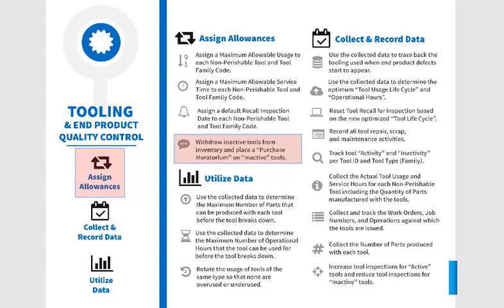So basically, if you implement a system to denote intelligent tool ID numbers and aggregate tools into family codes, then if you're tracking the usage of tools, you'll be able to determine if a tool is being overused or underused. If you find you have too many tools on hand and not enough usage, well, the first thing you can do is put a moratorium on and say, we will not be buying more of these tools, and maybe you can also sell some of the excess tools you have on hand.